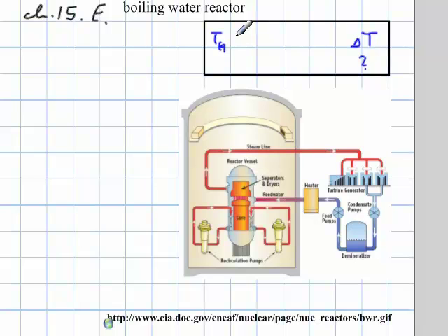And then the steam is going to go back to a cold temperature, respectively condenses to a cold temperature of 40 degrees Celsius. Of course, both of these have to be in Kelvin, so they're going to be 558 kelvins, off the top of my head, and 313 kelvins is what we need. It says that the plant operates at 3/4 of its Carnot efficiency. So at some point, I'm sure we have to determine its Carnot efficiency and then take 3/4 of that. The electrical output power of the plant is 1.2 billion watts, so that one is given.